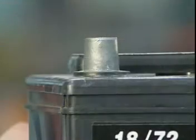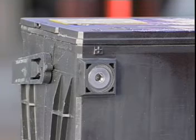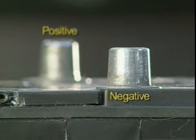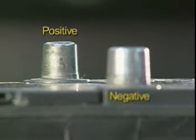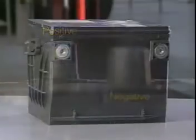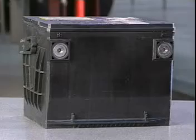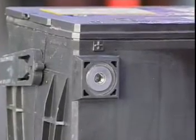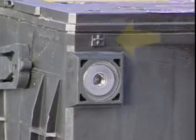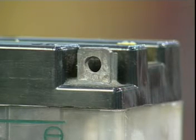The terminals themselves may be located on the top of the battery or on the side. Post or top-mounted terminals are commonly used on automotive batteries. The positive post will be larger than the negative post to prevent connecting the battery in reverse polarity. If the battery has side terminals, they are positioned in the side of the container, near the top. These terminals are threaded and require a special bolt to connect the cables. Polarity identification is by positive and negative symbols. Some specialty batteries, and those used in some imported vehicles, may use an L-shaped top-mounted terminal.